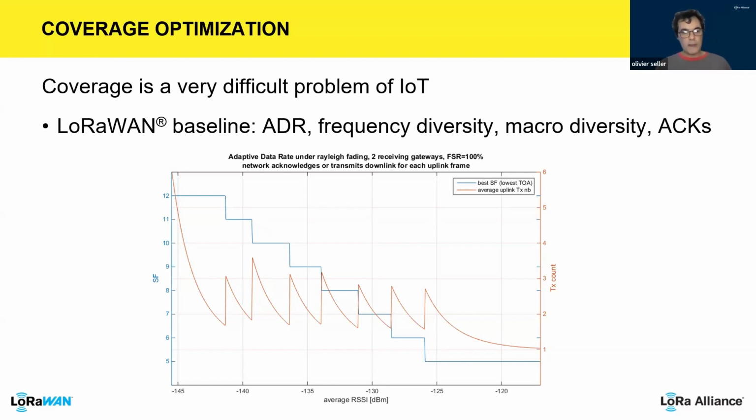If the network doesn't feel like sending acknowledgements or is not configured to do so, the number of transmitted frames will be slightly higher, probably between 4 and 5, because to increase the certainty of reception, there's going to be a little bit of waste of transmission, a blind transmission in the absence of feedback. But with this feedback, the number of retransmissions is fairly low, limited to 3.